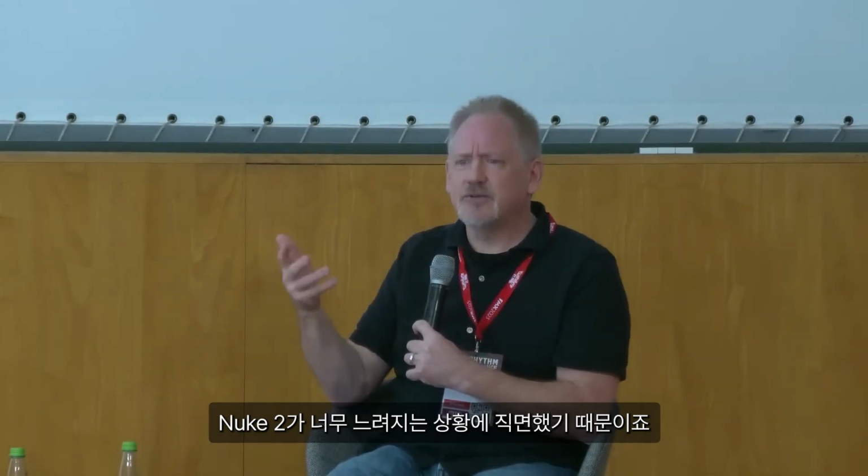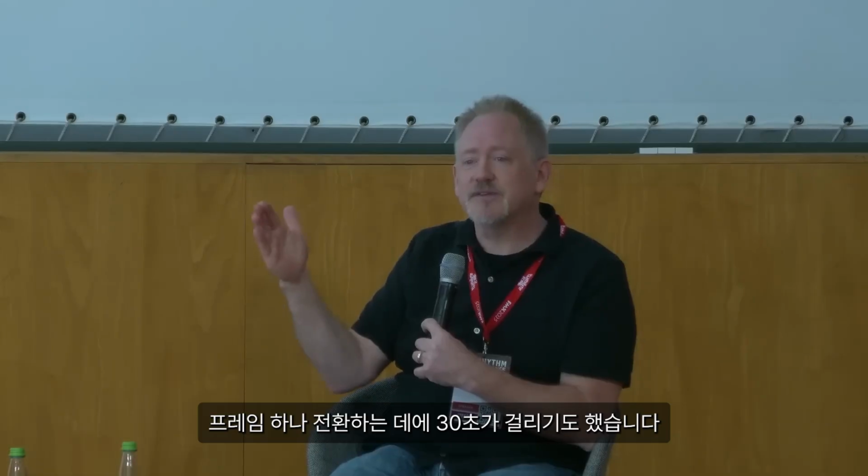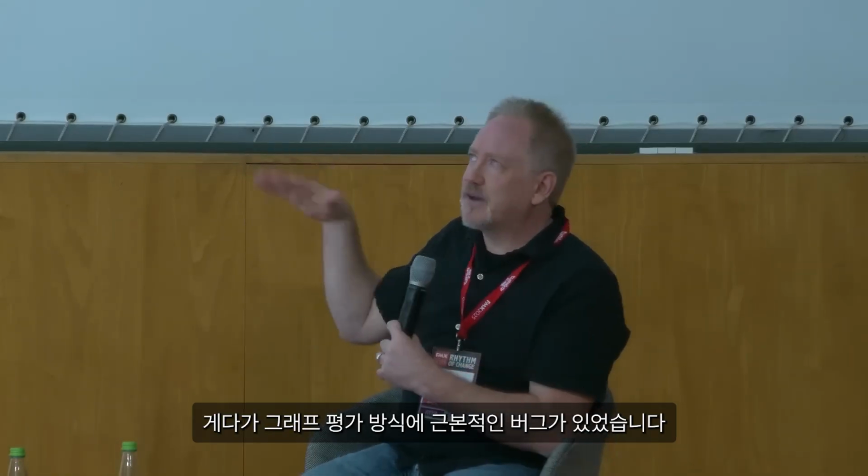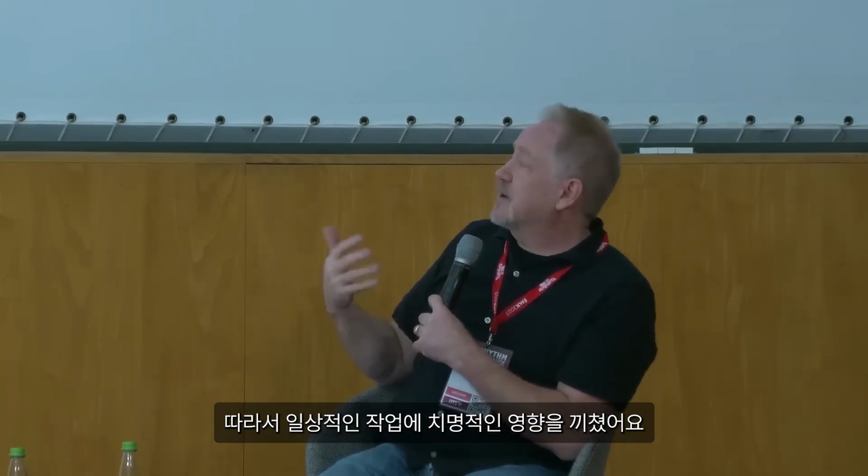So what did it for me was in Titanic, actually this is before Titanic, on Fifth Element, where Nuke 2 would sometimes be really, really slow. You would change frames, and it had to do with the complexity of the script. A script as complex as this could take 30 seconds for Nuke to change frames, because there was a fundamental bug in the way that Nuke was evaluating that graph.